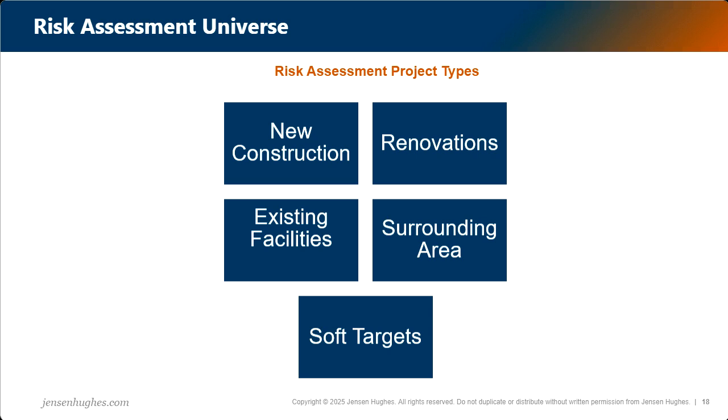And then we look at surrounding area. A building supported in either a campus environment or a large parking area with parking structures or satellite buildings, we want to take that into consideration. We talked about camera deployment. Well, in a camera deployment, as an example, you have to stay within that category cable range to maintain that power over Ethernet, and more importantly, your warranty for your cable. It will not pass if it exceeds the distance that's required for that warranty.